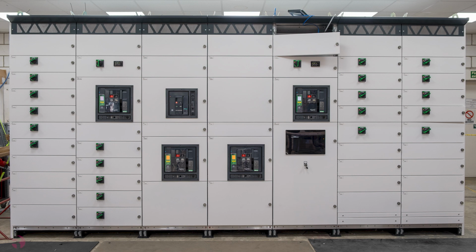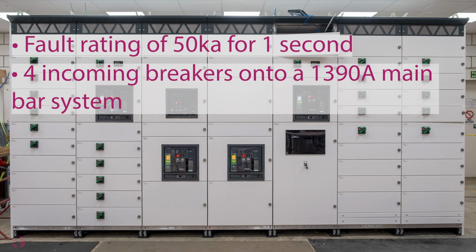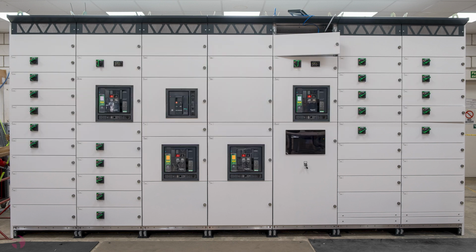Specifications of the board include a fault rating of 50 kA for 1 second, 4 incoming breakers onto a 1390 amp main bar system, Form 4B, Type 6 segregation with withdrawable plug-in feeders. The panel also features an IP31 ingress protection with top and bottom cable entry options.